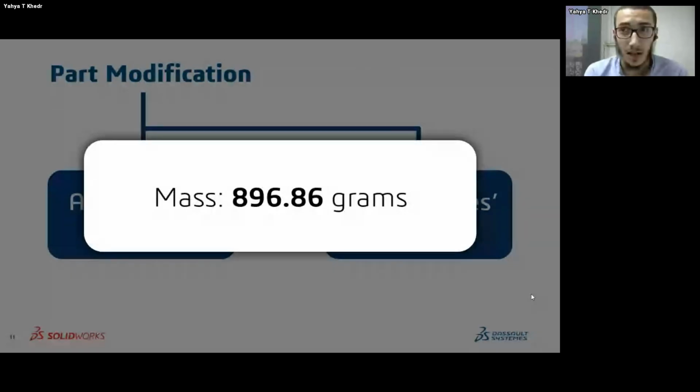The first thing is I didn't look ahead. I didn't understand what the modifications are going to look like, and therefore I created the design in not the best way possible. There were better ways to create this design, as we saw. There's also the other issue, which is I decided to do everything in one sketch and do everything in one feature because that's quicker, but that was actually taking me more time to modify it in the second stage.